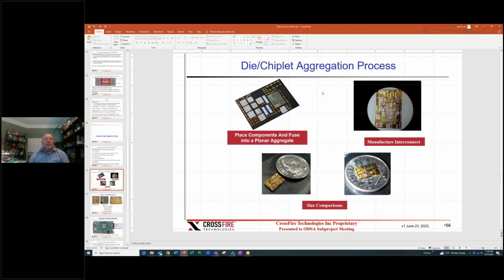This would be a replacement for people who are really trying to push the technology. And to your point, if everybody was at 5 micron pitch, I'm just using an example, we're a long way from that, then the registration error of connecting all these chiplets is a huge deal. And you have a way of addressing that.